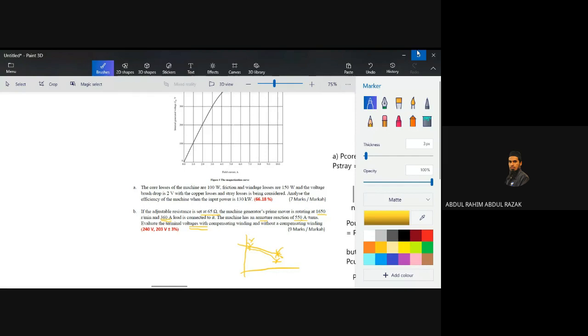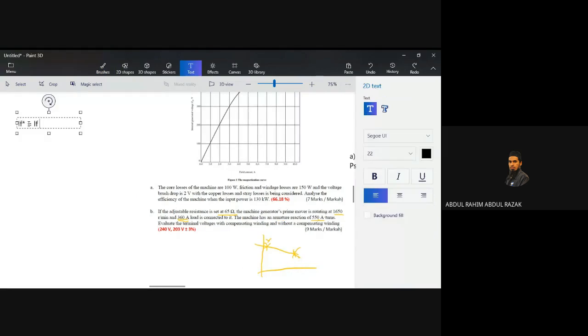IF now is equal to I field star, which is equal to I field of previous, I field of initial, minus armature reaction over number of field turn. So this is the equation that we should find.